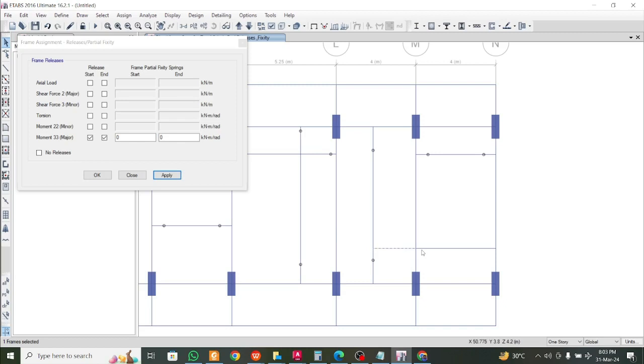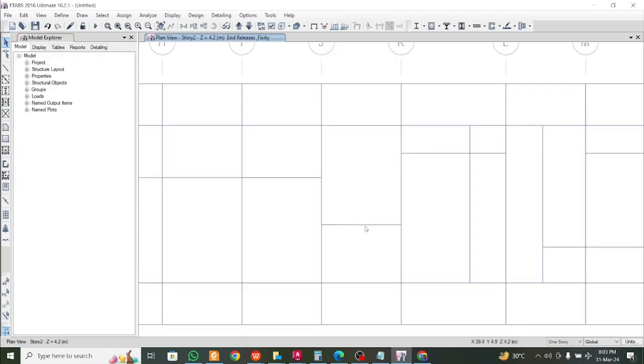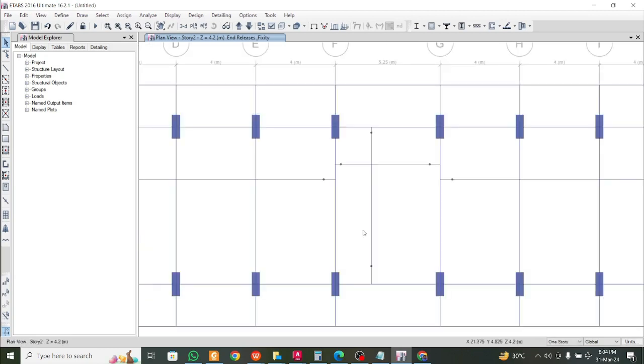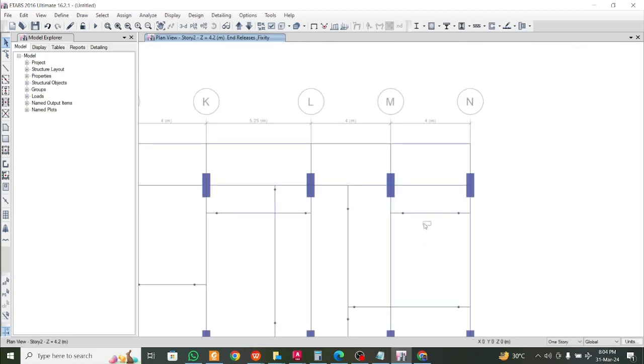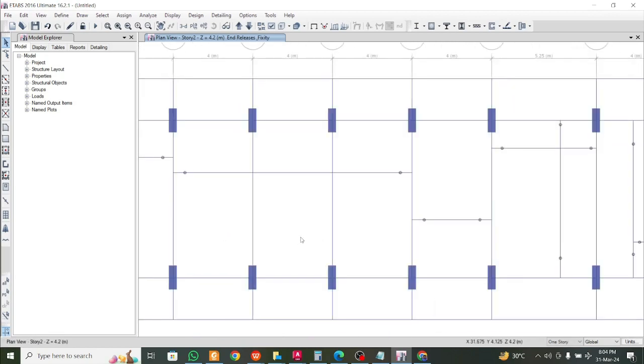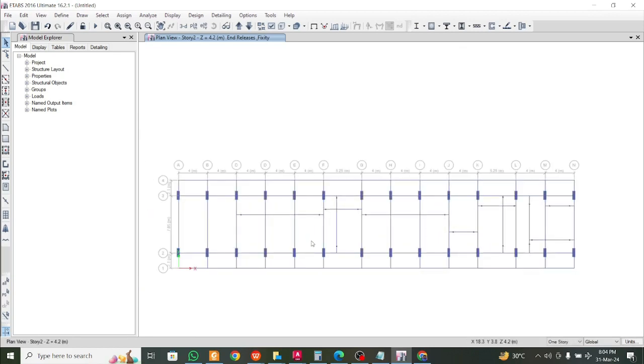Technically it should be at both the start and end, and should act as a point load here, but not sure I should do that. Okay, let me just do this. This will be definitely at the end obviously, and this is continuous, and this could be at the start. I think this is okay. If you disagree, then you can let me know in the comment section with the reason. That's I teach you, you teach me, like Ash said. Okay, so now this secondary beam is done, and all the properties are also assigned in this floor.